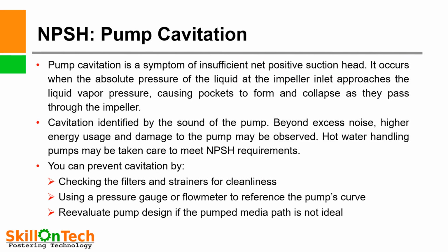NPSH, net positive suction head, pump cavitation. Pump cavitation is a symptom of insufficient net positive suction head. It occurs when the absolute pressure of the liquid at the impeller inlet approaches the liquid vapor pressure, causing pockets of bubbles to form and collapse at the discharge side of the impeller when they pass through the impeller.